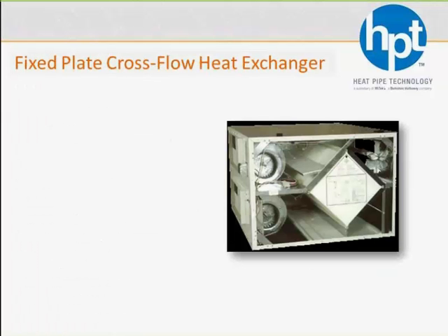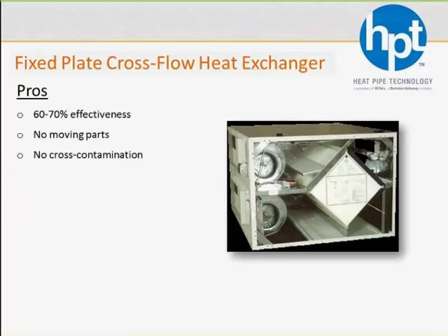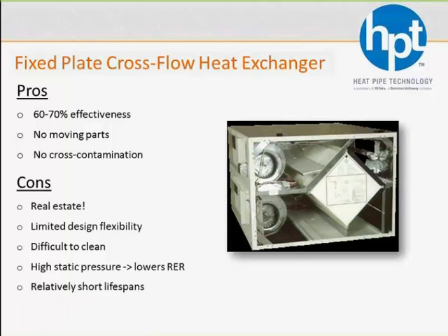Another device out there that will meet this 50% mark is the fixed plate. They're not as effective as wheels, but they're still up in the 60 to 70% range. There are plates that can recover both sensible and latent heat, so they'll meet that enthalpy mark. No moving parts, so you don't have to pull any power to the plates like you would a wheel. They don't have cross-contamination concerns like a wheel would, so you could use them in those scenarios.